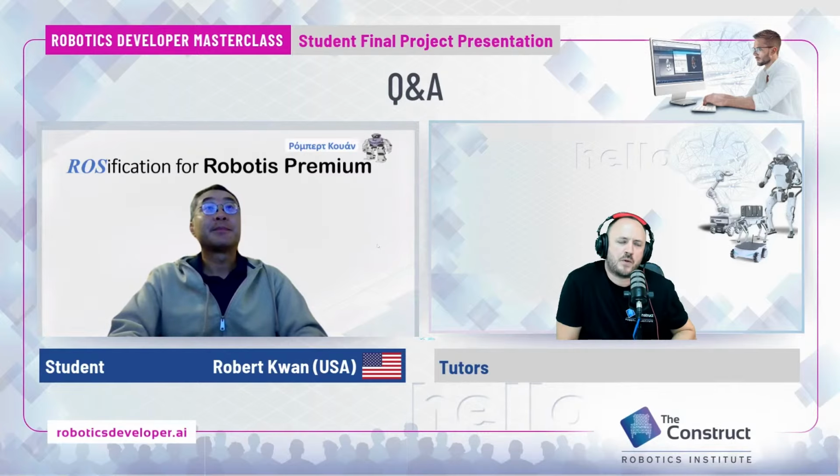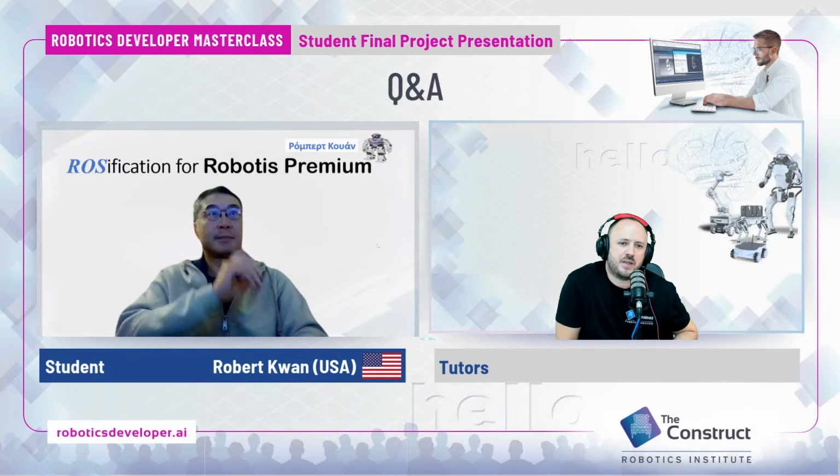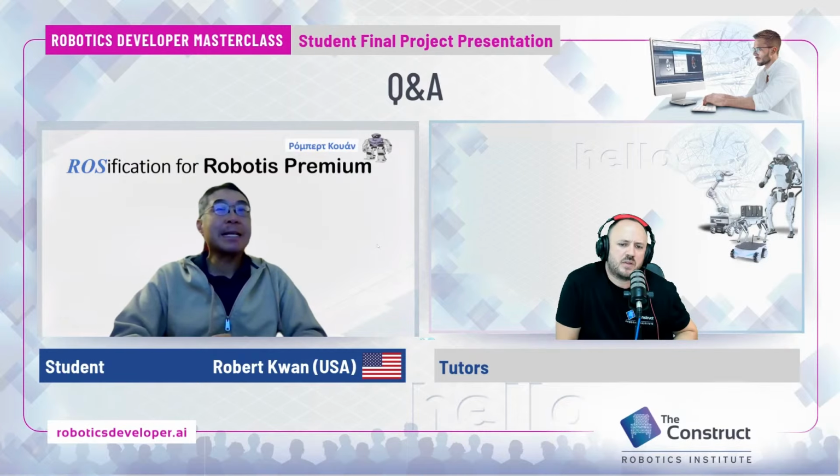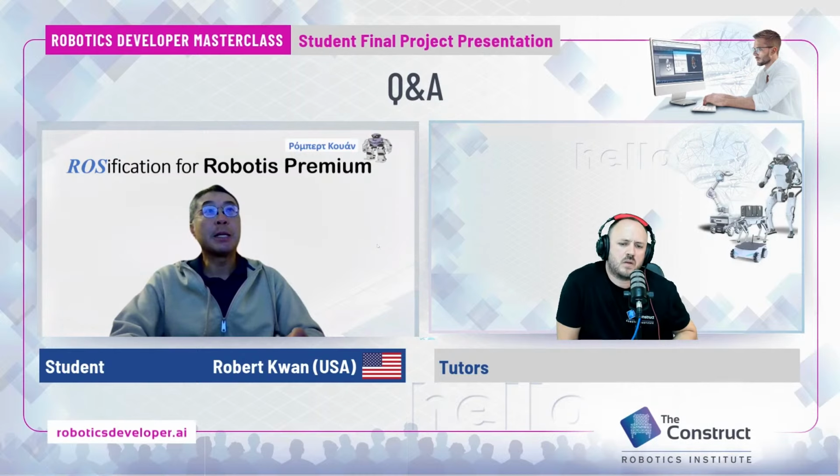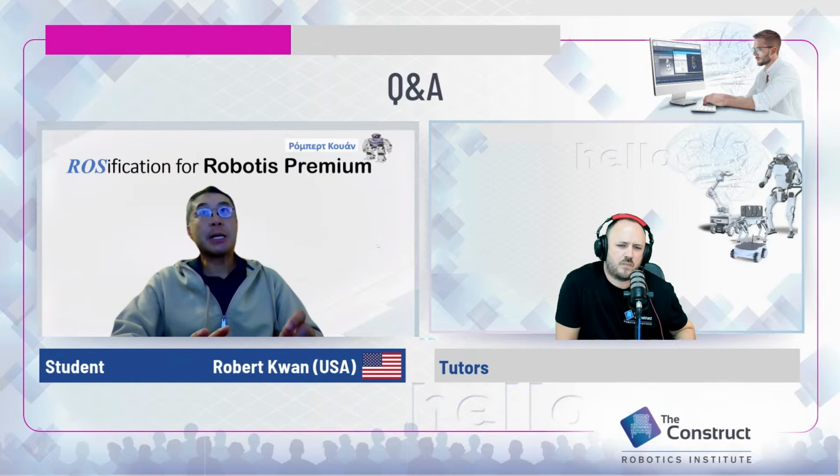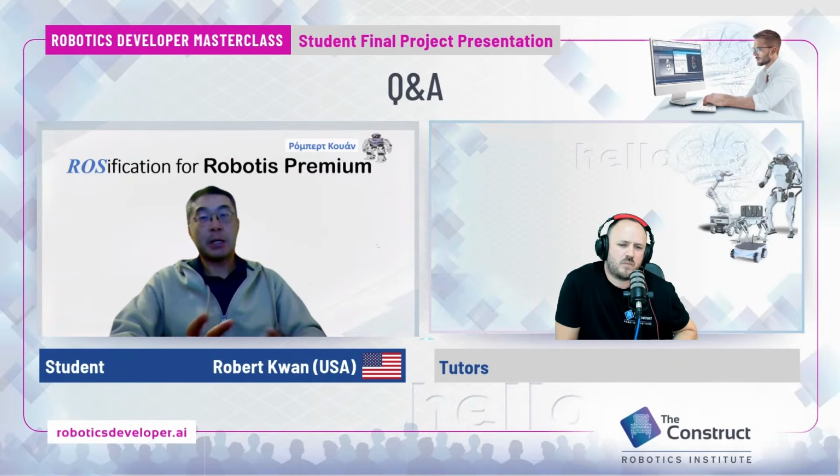From the ROS side, what type of messages are you sending to the motors? Right now I'm using ROS to control it by setting the follow trajectory parameter. That is mainly just for position control. In ROS2, position is defined in radians, right? That's why, as I mentioned, the motors accept hard-coded values in their registers, so I had to do another conversion formula to convert from radians back to the values that the motor register can read. Okay, I understand.